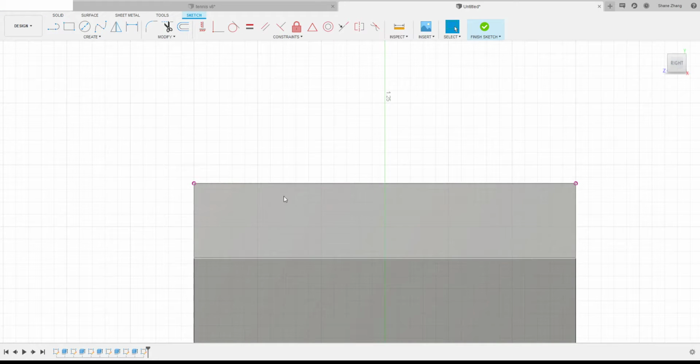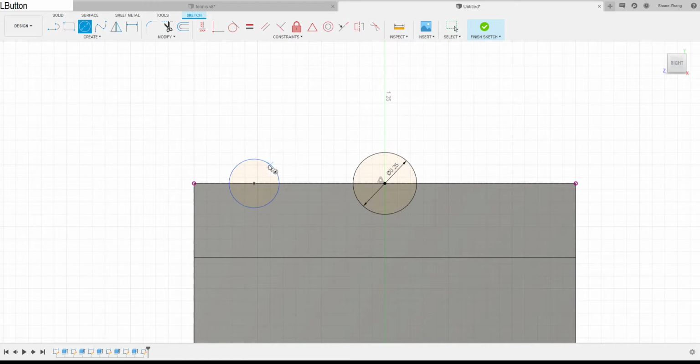Okay, so still looking through the right plane, the circle in the middle is 0.25 in diameter. Then we have two circles on the side. You can make two circles, or you can use this symmetric. Once we constrain this circle, you can mirror to the other side, or you can do a mirror inside the sketch. So either way is fine. And we can also use a constraint instead of another dimension. So I want equal. I want these two circles to be equal, and that's one constraint.